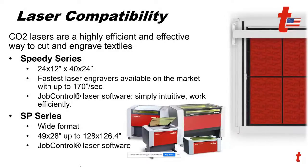So moving forward here, laser compatibility. With fabric and apparel type applications like that, the CO2 lasers are the primary application. There's a lot of lasers out there, most of which are CO2. And CO2 is the right wavelength and type of laser for processing fabrics because it works the best with the materials. Other lasers like fiber lasers really won't do anything with this material. So CO2 lasers are the most efficient way to cut and engrave any type of textile.